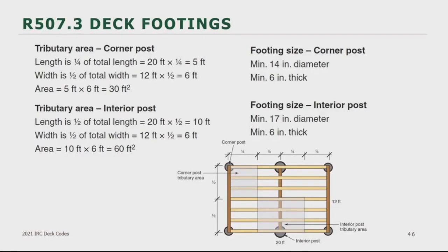From here we can go into Table R507.3.1 and find our footing sizes. Table R507.3.1 provides options for both square and round footing sizes. The example here only gives you the round footing diameter sizes.